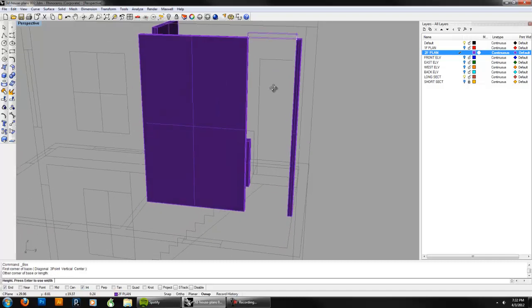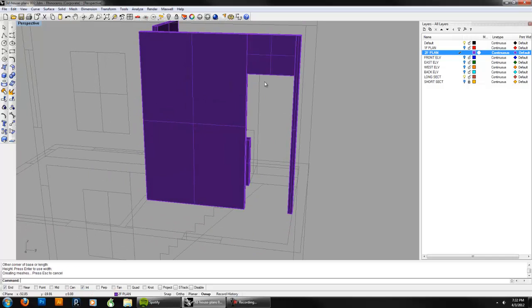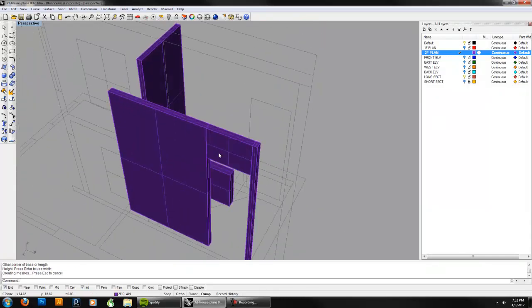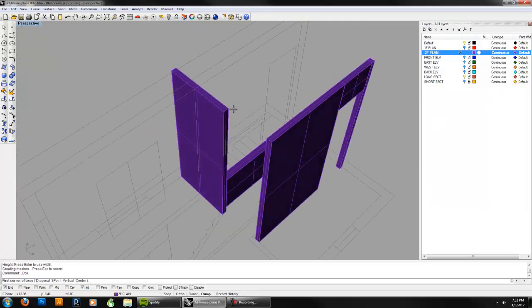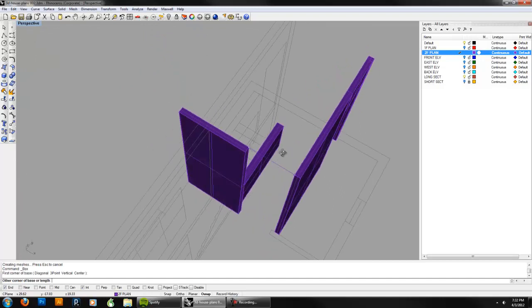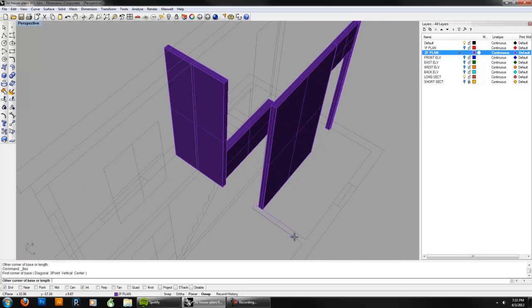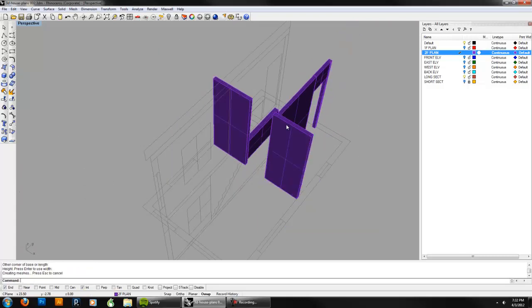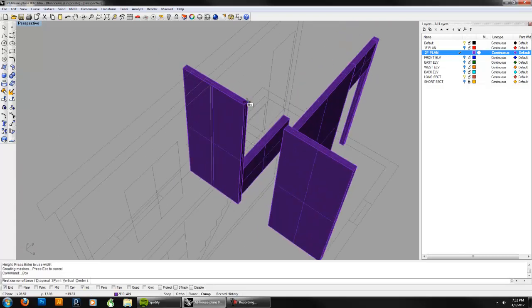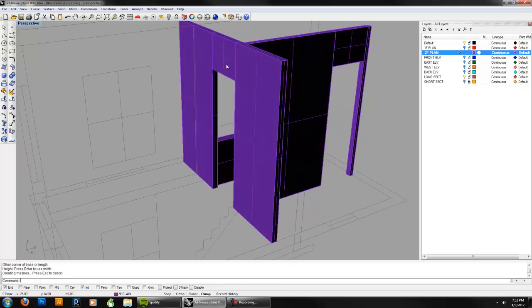You don't need all the drawings, because if you have other drawings that reference each other, you can get, let's say, the lintel. The lintel here is going to be, actually I need to finish this wall here. The lintel is going to be similar though, so you can always snap off of a similar lintel condition, like that. So this one is going to relate to that one. Okay, I'll do that again here.